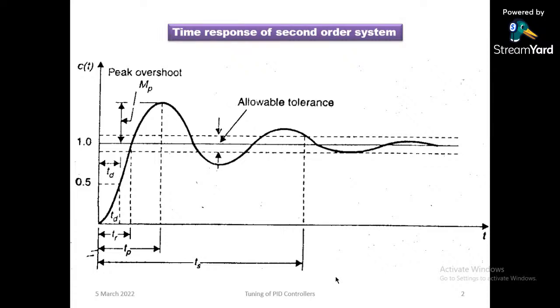Okay, and in this workshop I am going to connect all those controllers or compensators in cascade with the existing plant. In cascade, we are seeing just a cascade compensation, right? In the control system design subject also we have seen lag or lead compensators, right? Lead compensator is used to improve the transient response, that is to improve overshoot, settling time, rise time, delay time, peak time, these parameters. Now lag compensator is used to improve the steady state response or to reduce the steady state error, correct?